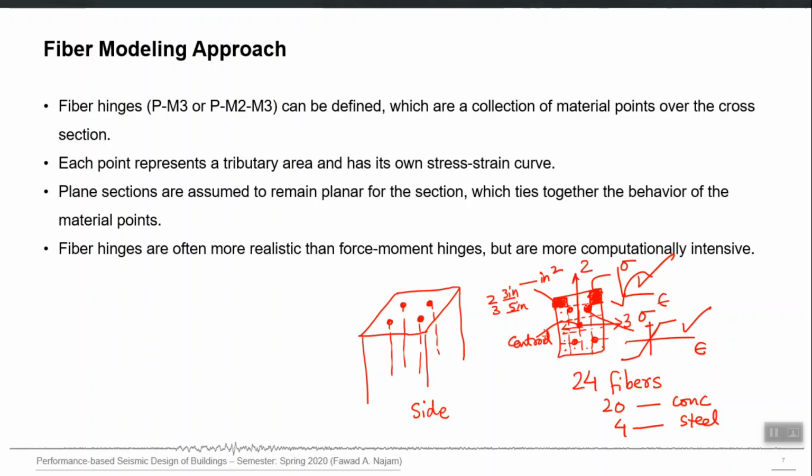So just compare it now with that plastic hinge approach, where we were directly calculating or determining the member level response and giving it as an input. Here no need for that. Directly make a material as nonlinear. That nonlinear will ultimately result in a nonlinear moment rotation curve, right? Which we were previously taking from ASCE 41 and giving it as an input, right?